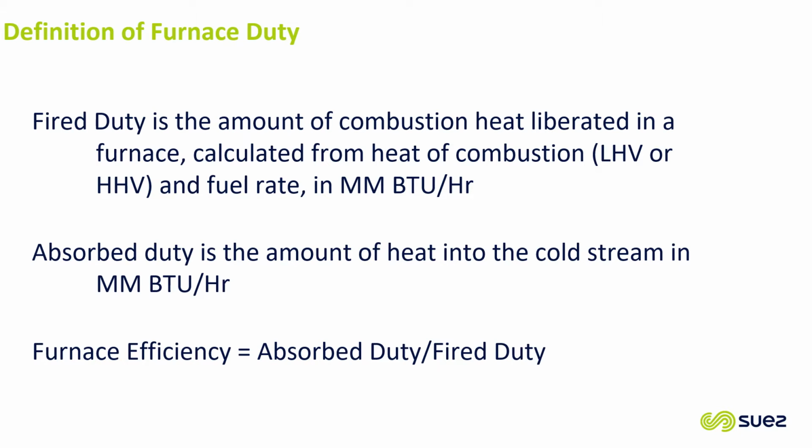The absorbed duty, on the other hand, is the amount of heat that the cold stream gets from that firing. And that's going to be calculated by some of the calculations that we're going to discuss in the future. An important term to remember is furnace efficiency. One way to describe that is the absorbed duty, the amount that's absorbed by the cold stream, divided by the fire duty, the amount that the furnace puts out.